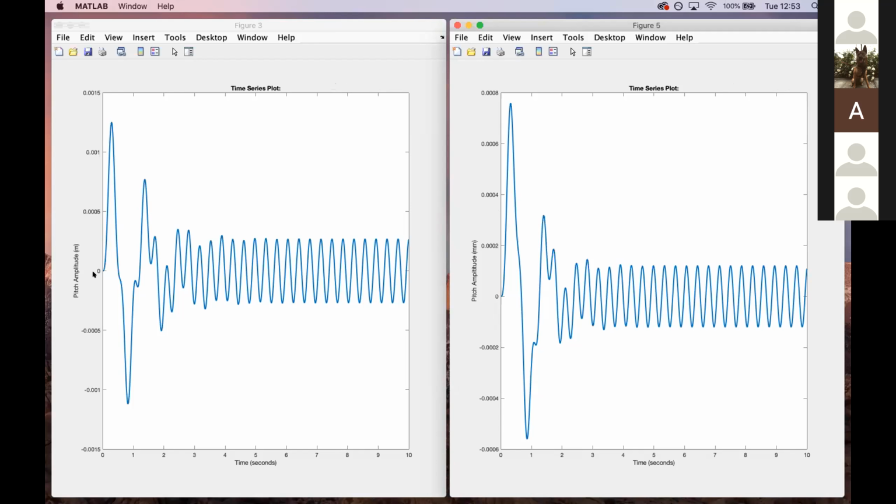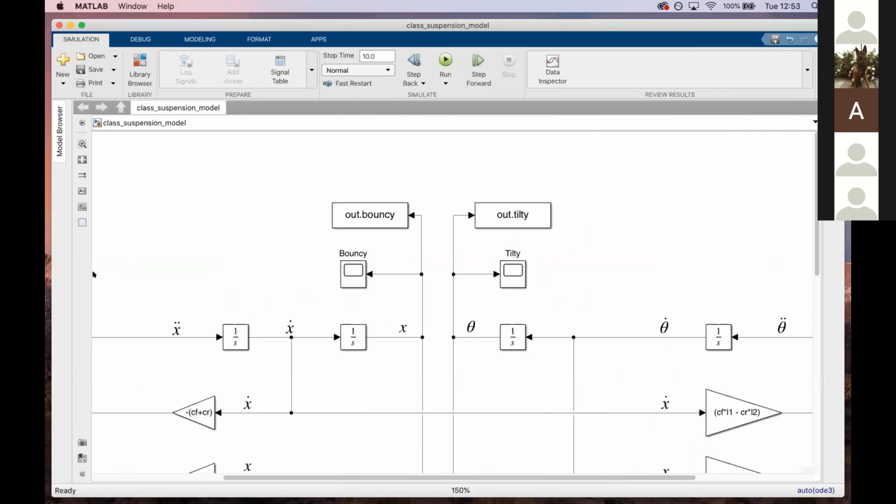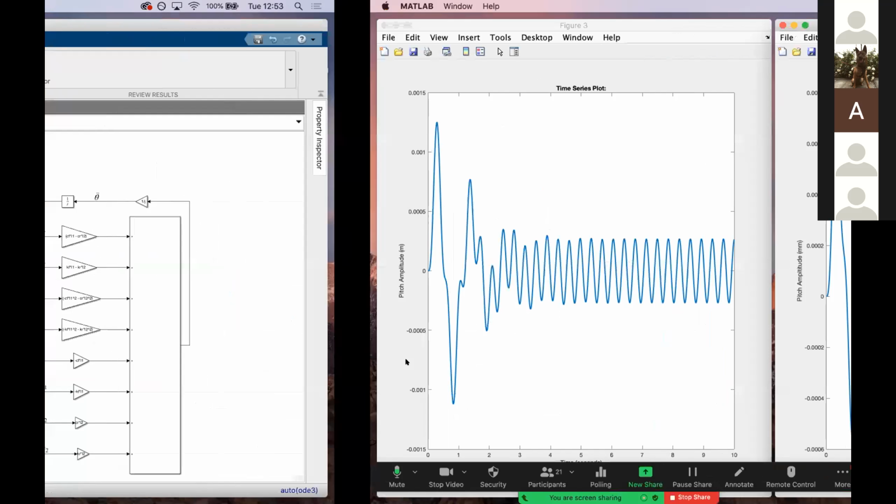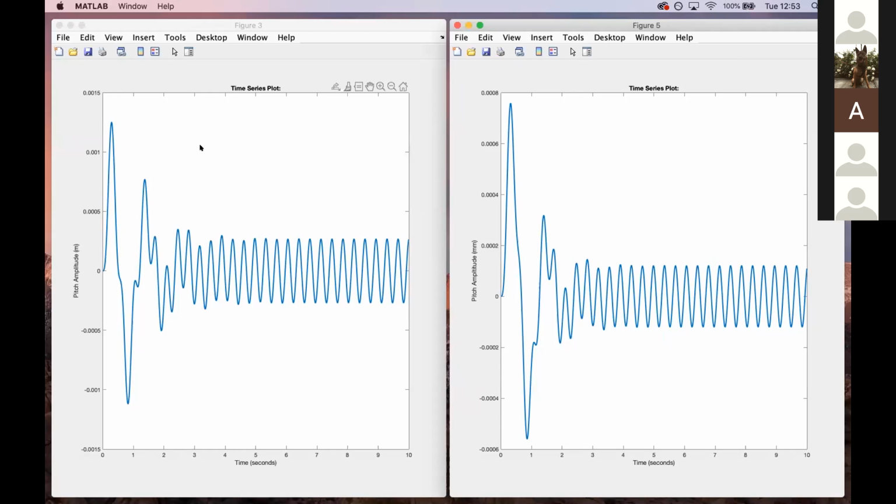Yeah. Okay. So are there any questions though before we finish today? And of course, if you didn't get all of the modeling done or the script, I'm going to upload this as soon as it's done processing on YouTube. But your job will be to look at our response here. You're going to look at the maximum value that we have. Well, actually, you have to look at steady state, right? So you have to look at steady state. So you're going to adjust the damping coefficient and the stiffness coefficient until you get values that are less than the required constraints of the lab.